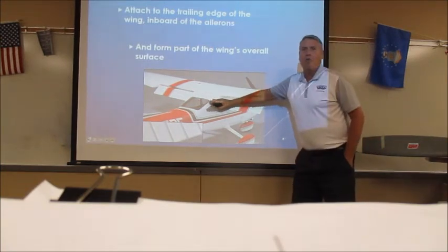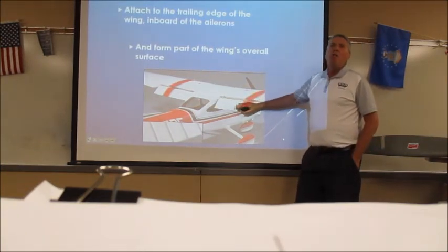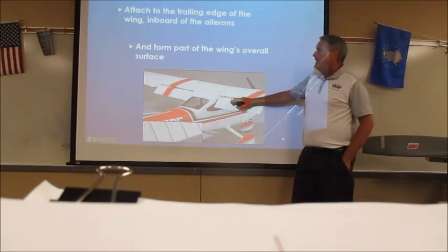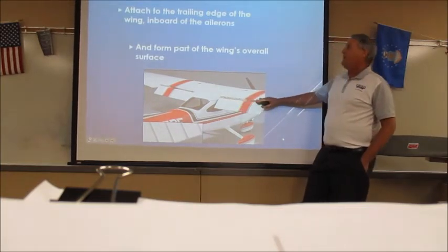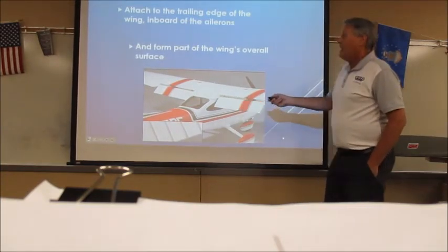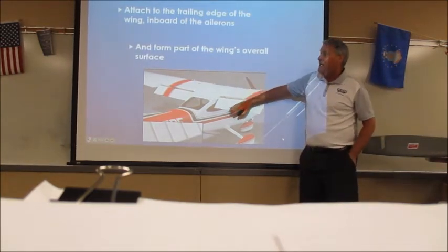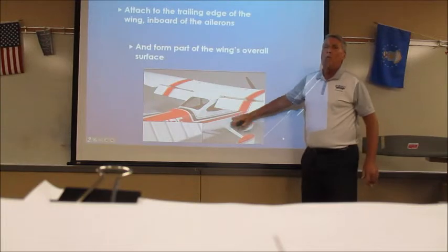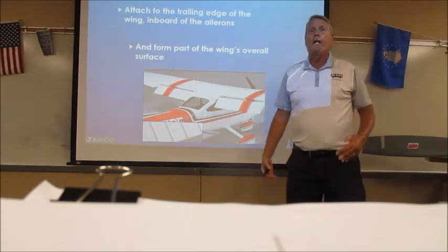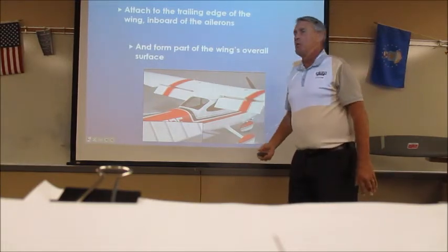They're part of the wing. When they're not deployed, they're actually part of the wing. And then when we deploy it, you can see how we increase the camber of the wing surface, and it helps us create more lift at slower speeds.